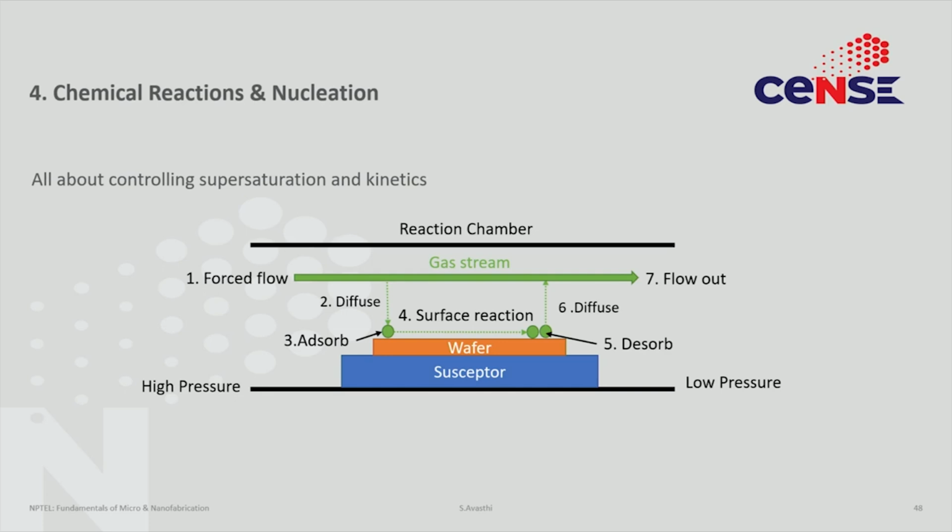So, once the precursor has adsorbed on the surface, then it must suffer the chemical reaction that would eventually form the film that you want to deposit. So, let us talk about chemical reactions, and once the material has formed, that is just a molecule of the material, it then has to adjust its way on the surface so as to form a crystal. Given that we are depositing solids, this diffusion or reorganization of the molecule on the surface can be fairly non-trivial, and we will look at some of those details, which is generally understood under the concepts of nucleation. So, first, chemical reactions.